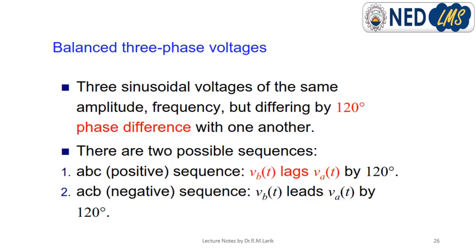What is a practical example of a balanced system? Three-phase motors, because the three-phase motor windings have the same reactance value in all phases, as they are manufactured by the same vendor, same coil diameter, same resistance, same reactance. So the three-phase motor is a perfect balanced load example.